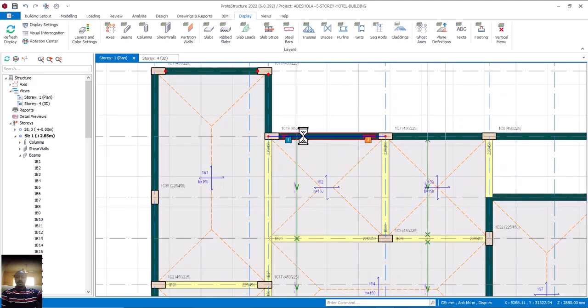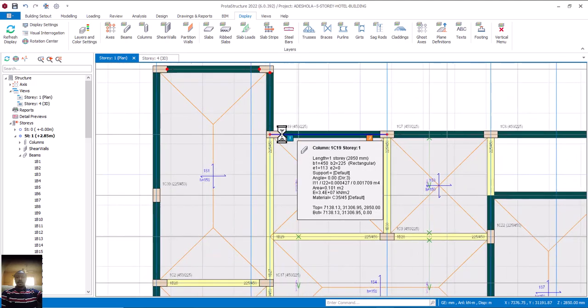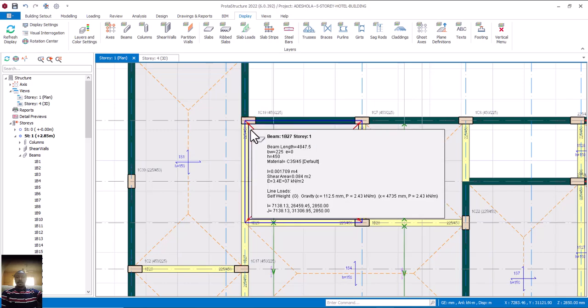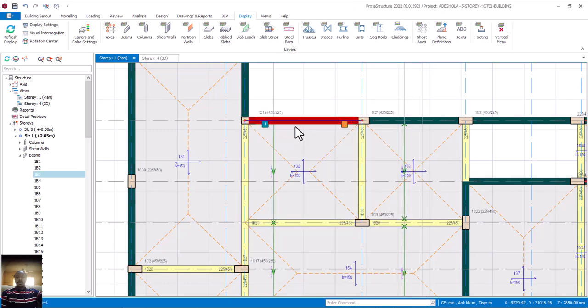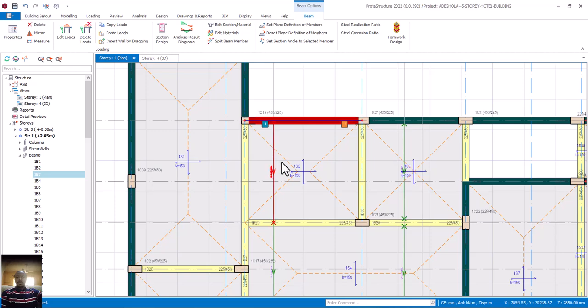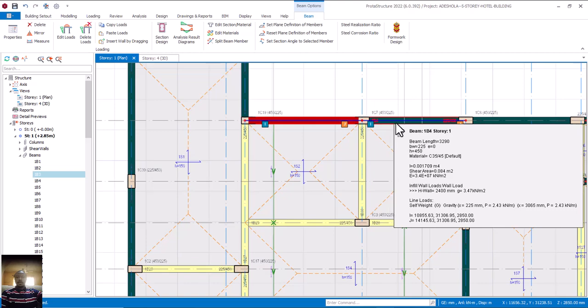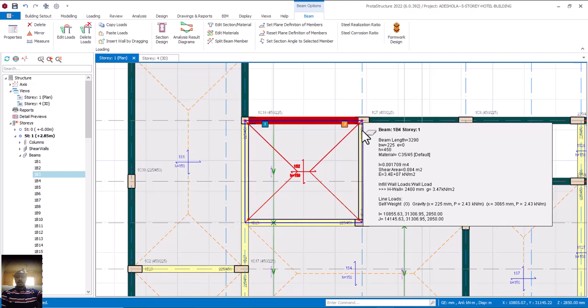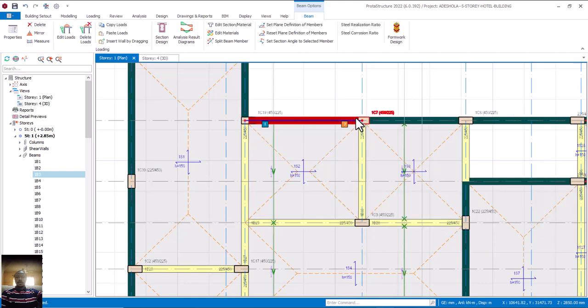So looking at this other side too, if I have to draw the diagram of this particular beam, it's going to come like this, and at this place it goes like this, goes up like this, and comes like this. That is why at this point we are having that hogging moment: because there's a continuation of this beam on this other side. So that is why you notice that we normally provide reinforcement around this place.